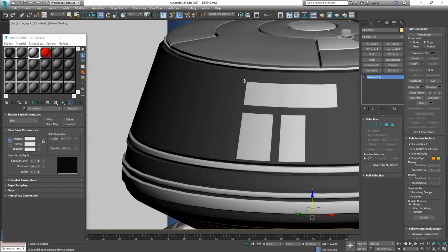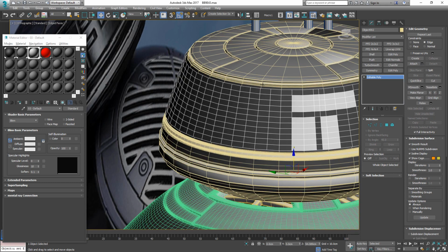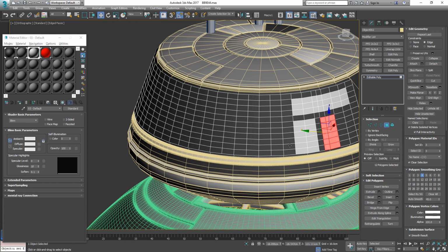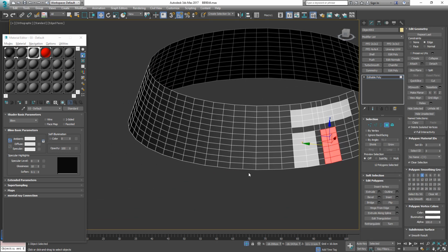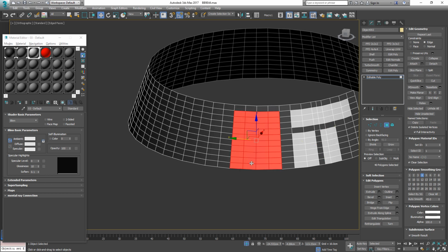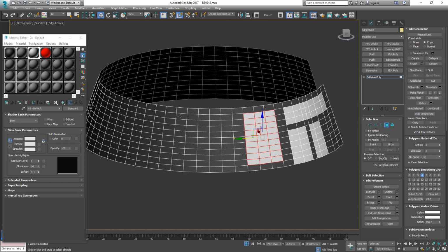These two here. And now let's just carry on by using our polygon mode. And we can also draw a selection, by the way. I'm just going to go here into our isolation mode, and drawing a selection, and then with Alt we can take some away, and that might speed things up a bit here as well.